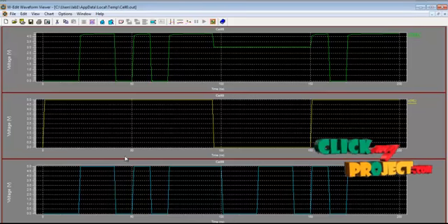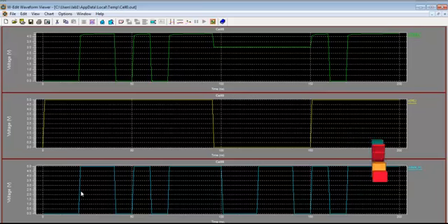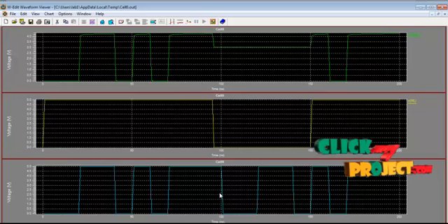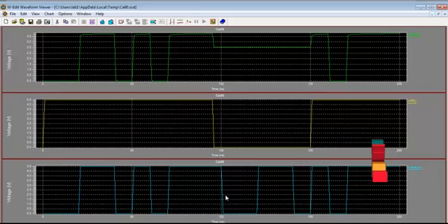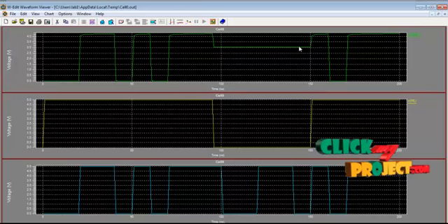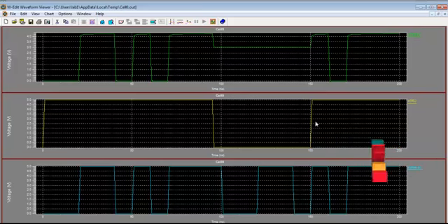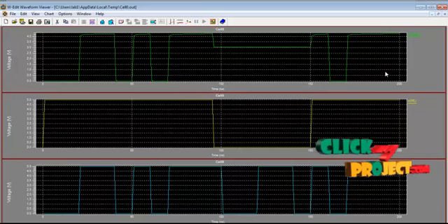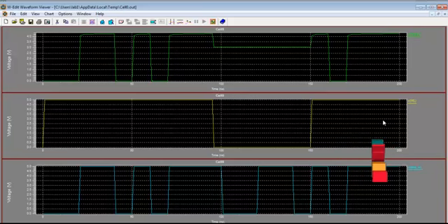When the write signal is 1, the data inputs 1 0 1 1 0 1 0 and 1 1 are written. With the write signal deactivated, the input data is not written and the stored data is read out. When the write signal is activated again, the inputs 1, 1 0 and 1 1 are written to the output, giving the final results.